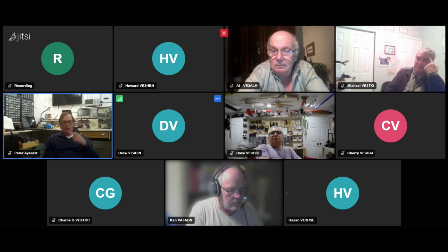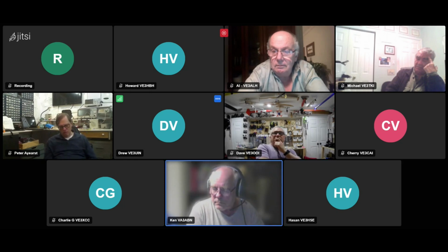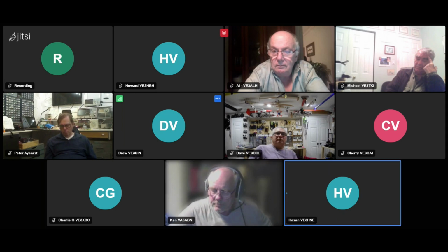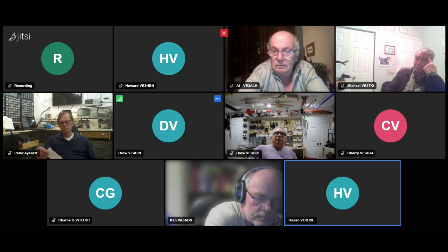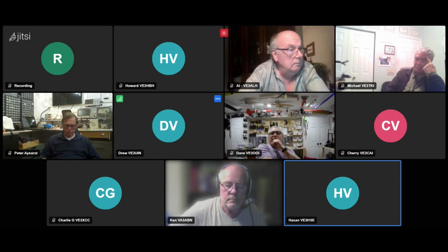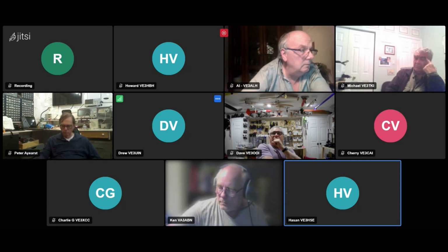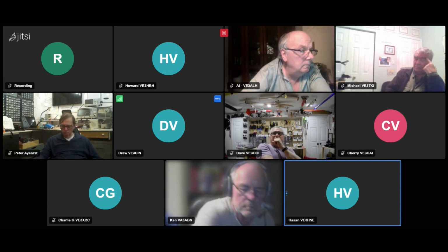I might have an answer for Dave on that. Can you hear me, Dave? Yeah. So I think the reason they do that, they have a hot noise source and a cold noise source. It's related to the Dickey radiometer. The reason is absolute noise measurements are tricky because you can never have a noise-free measurement as a baseline.